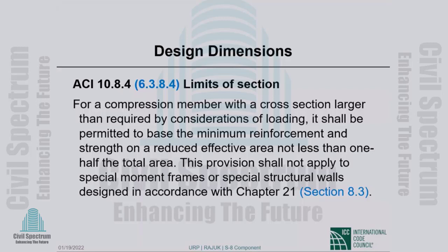And when you have reached 1%, you switch to even a lower concrete strength. So at the very top of the building, we typically end up with 4,000 PSI concrete and 0.5% reinforcement, not 1%, because the column in those parts will be much larger than needed for the loads. So we go with 0.5% reinforcement.